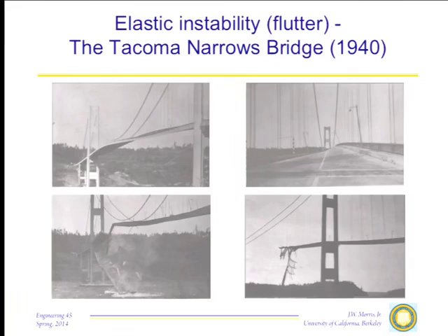The reason was that in order to design around this kind of problem, you've got to be able to identify the natural frequencies of your structures. Now, this can be an enormously complicated thing. If you're in mechanical engineering, maybe study vibration a little bit. You not only have to worry about the primary vibrational modes, you have to worry about all the harmonics of the vibrational modes. And if you excite the sixth harmonic, which you may not even see in normal operation, you excite that thing to instability, you've just lost your part.